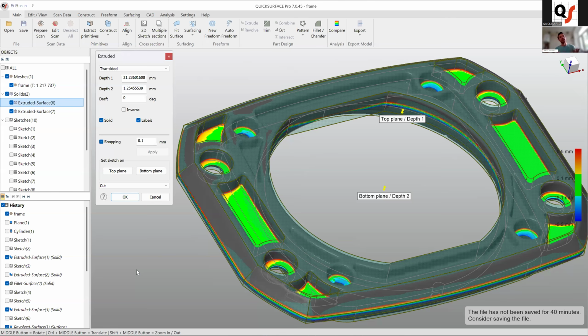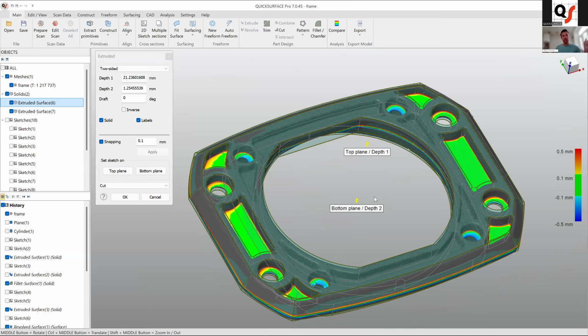Plus one thing is noise that comes from the scanning itself. Another part is the surface of this part. Third part is the coating. So you can have some kind of paint that will have orange peel, or you can have some plastic paints that will be specifically designed to have some grip there, so it will be even more noisy and things like that. Of course, you have to consider this by yourself and just, yes, don't go too low because mostly all the scanners have some noise.